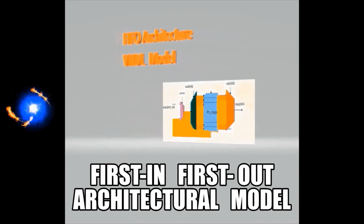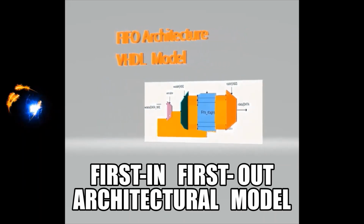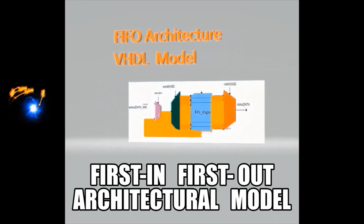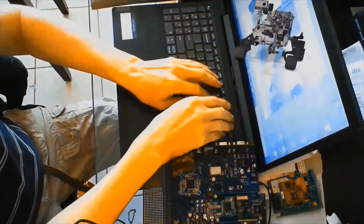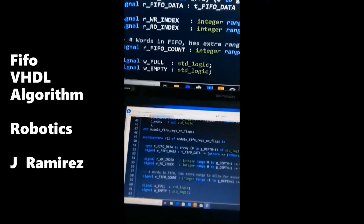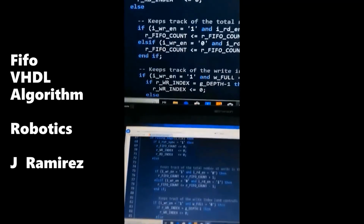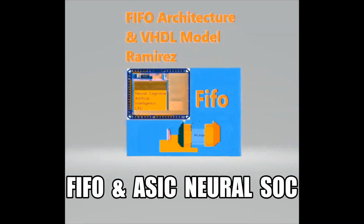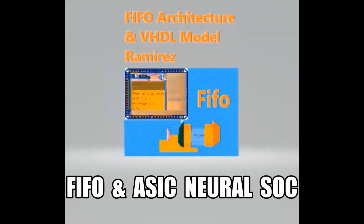In order to write data into the FIFO, first in, first out, first push the data onto the data in bus and then strobe the write enable input high for one clock cycle. It will write whatever is on the data in into the FIFO's internal memory. When writing in bulk, the write enable signal is left high while changing the data on the data in bus each clock cycle.